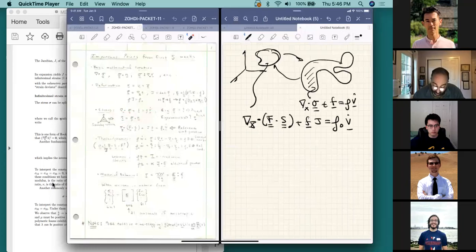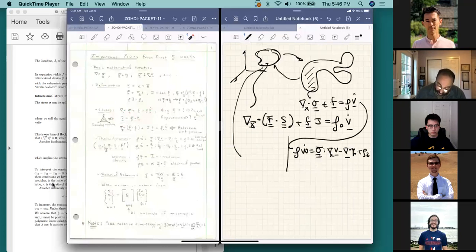And by the same token, the differential equation that lives over here for the first law of thermodynamics is rho w dot equals sigma inner product with gradient of v minus the divergence of q plus rho z. And over here on this side, the analog is rho 0 w dot equals S inner product with E dot minus the divergence of q0 plus rho 0 times z.